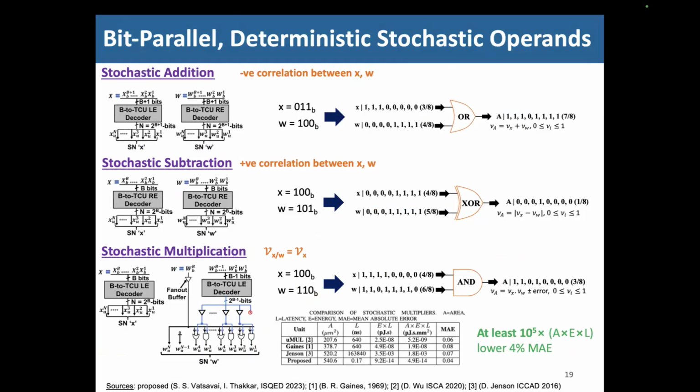So we can use the noise, but then the numbers that you generate out of that noise will not have the deterministic bit position correlation that you need, especially in multiplication, subtraction, and addition, to minimize the error. So if you want to do stochastic arithmetic, a deterministic approach would work better for error reduction than a pseudo-random or random approach.